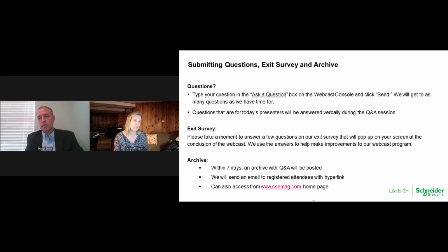Okay. So this is kind of a follow-up question. What are some best practices or tips for finding the delicate balance between a small footprint and a comfortable working environment? It depends on the equipment itself. I like using the fusible disconnect switches because we can really fit a lot of capacity into a very small footprint, but that is not a comfortable to maintain footprint.